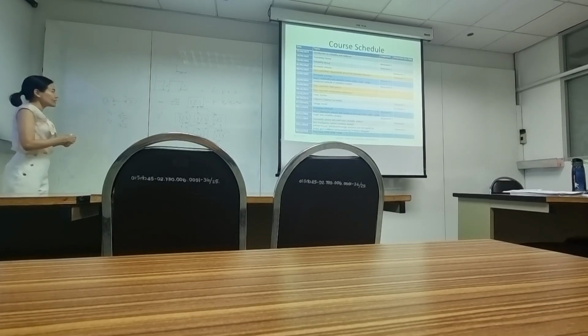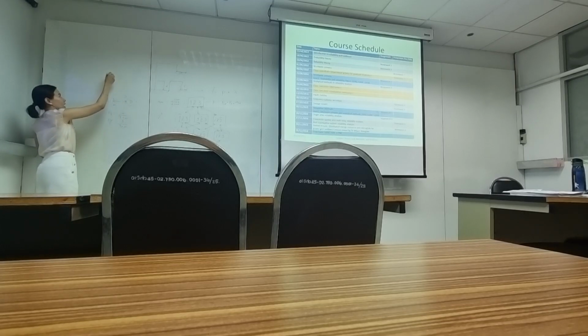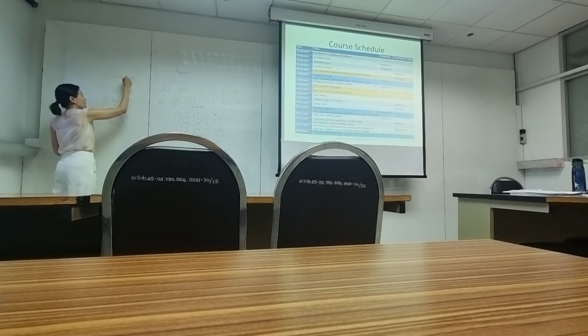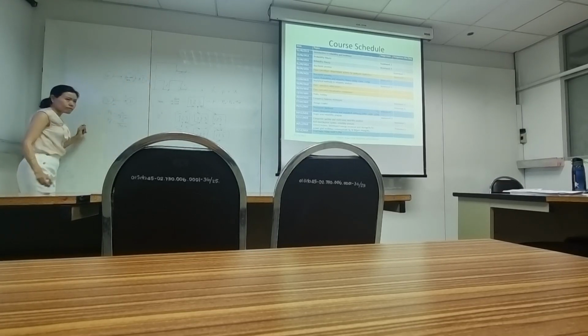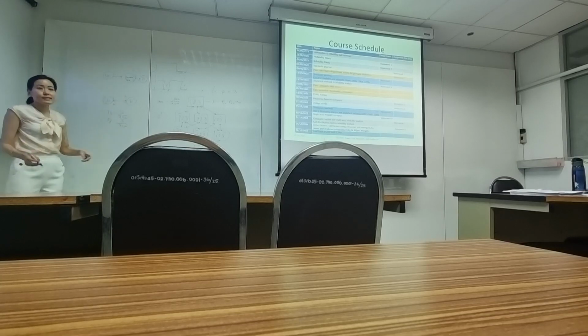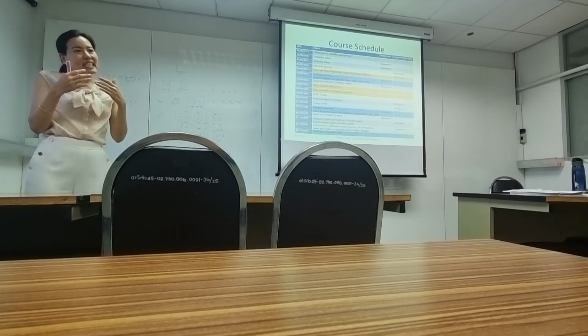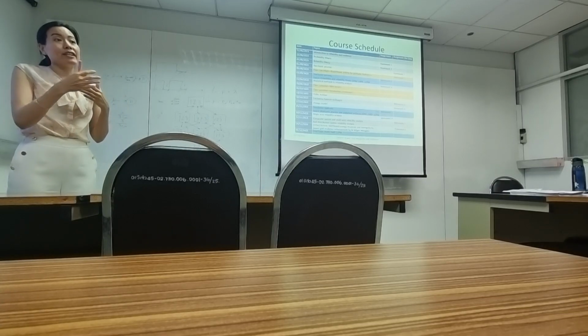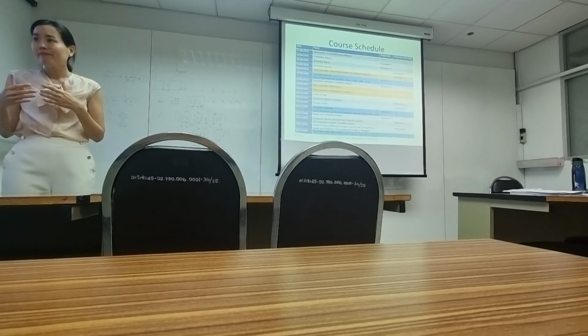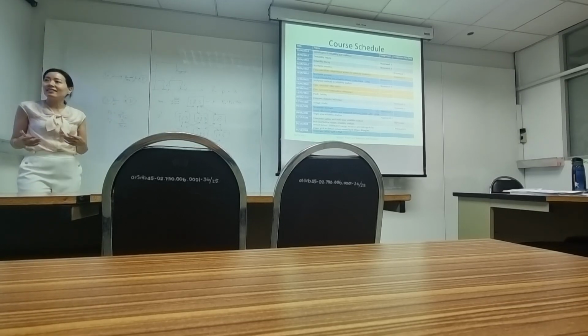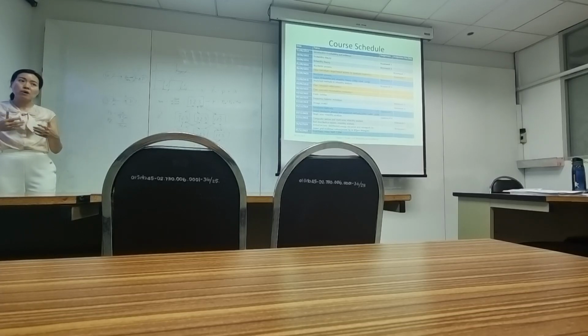A generator may have an up state, and instead of just a down state, a derated state and then a down state. What does a derated state mean? It means that the generator cannot supply capacity at its full capacity, maybe only half, depending on how it's running. All these things depend on your problem.